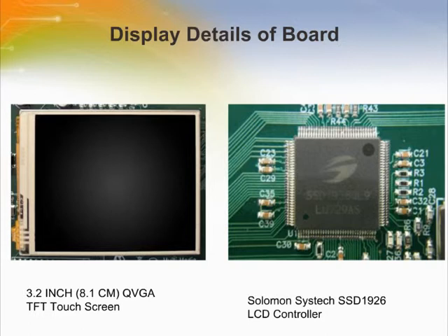The Multimedia expansion board has a 3.2-inch QVGA TFT touchscreen as shown in this page. The display is controlled by a Solomon Systech SSD1926 LCD controller. The display controller may be configured to use an 8-bit or 16-bit interface. The display also has a resistive touchscreen and backlight controls.